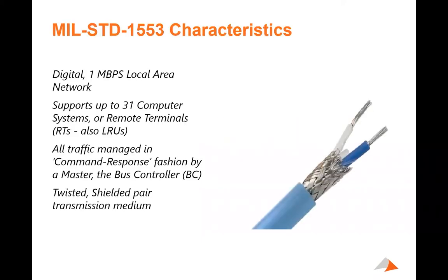And what it specifies is a local area network that travels at a blazing 1 megabit per second. That's not bytes, it is bits. And so your effective throughput is somewhere around 800 kilobits. Now, the thing that makes it still viable today is that it's command control. It's very fast in response time, being in that 4 microsecond response time, and it's a high voltage signal as compared to doing Ethernet or even some of the other networks.